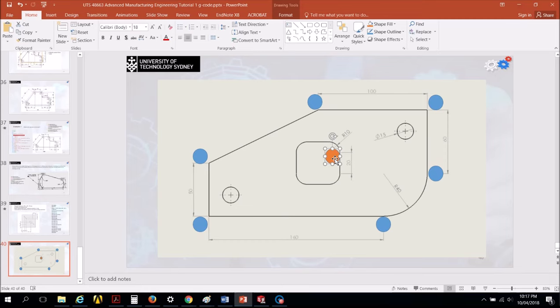So I did this cutting. I will remove the vise. I'm going to use the bolts and the nuts. I have to put a pad below with a thickness of, let's say, 5 millimeters to protect the table while I do the profile cutting. Okay, now I fix the part, and I know the value of the datum point, which is this point. This will be my datum point. Let's have an arrow there.